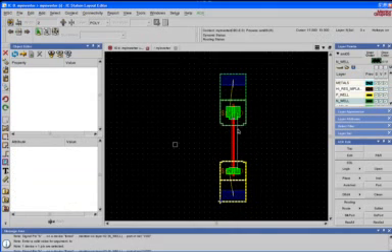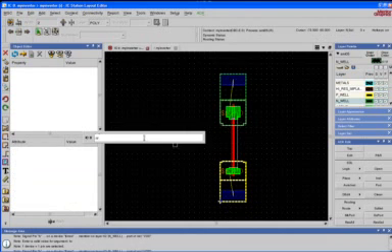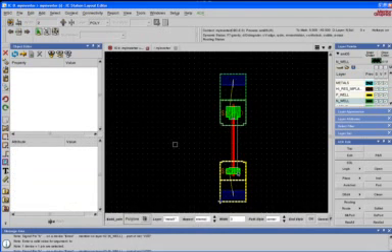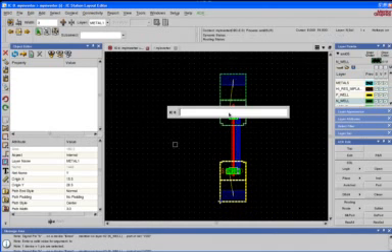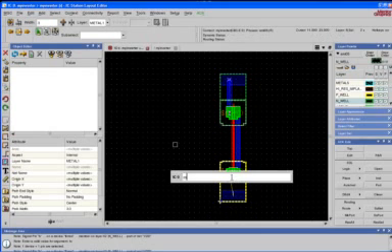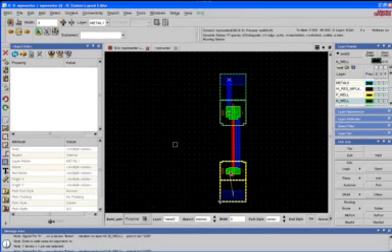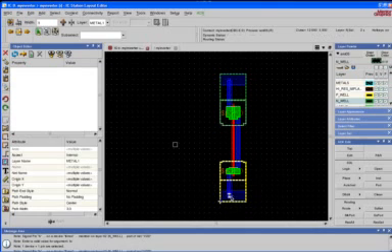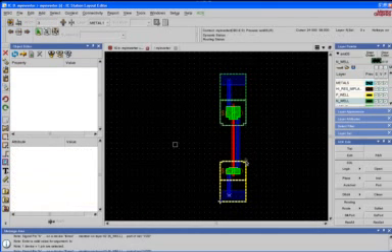Let's connect the metal line for these two, and a metal line to VDD, metal line to ground. Space, M, enter. This creates a metal line of width 3. Notice how the overflow lines disappeared as soon as we wired them up.